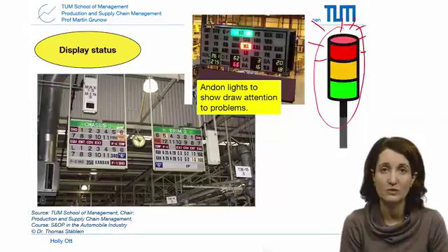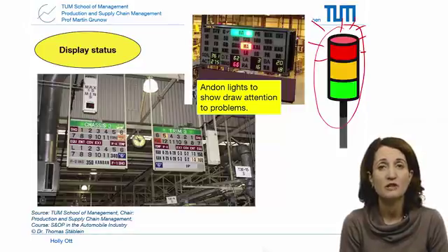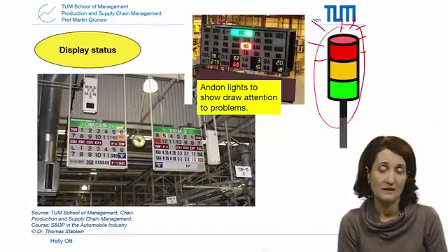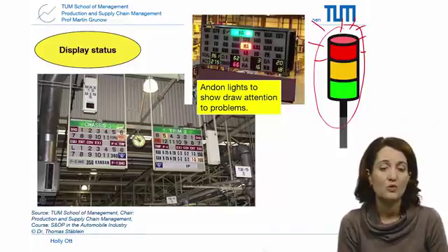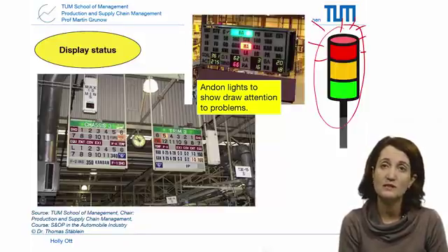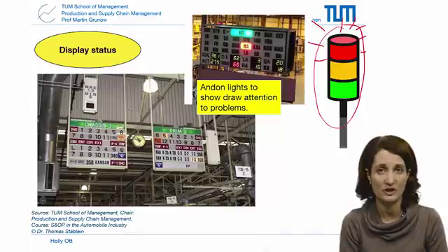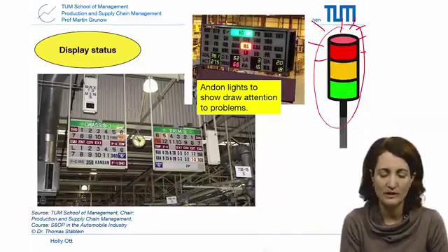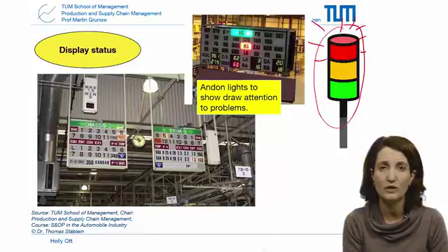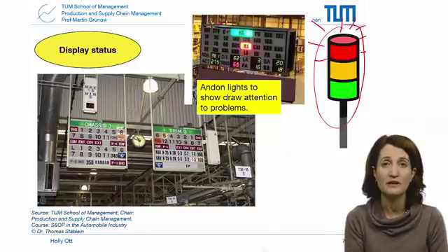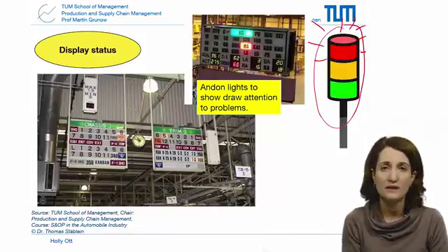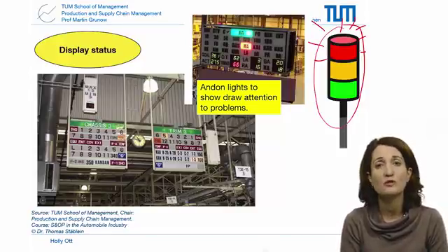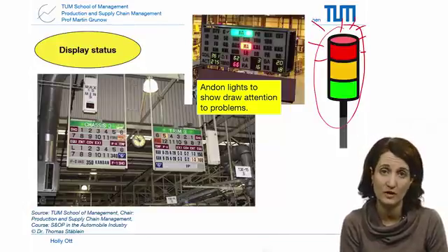What's very interesting here is the origins came from the original automated loom company. These looms from Toyota Sakichi would stop immediately if one of the threads broke. So the machine itself could distinguish between a normal situation and an abnormal situation. It's important because as soon as there was a defect, the operator would push the button or pull the cord and the line would stop. Of course, that means nothing can be produced at that time. But you're avoiding producing defective products, avoiding additional waste, and drawing attention to the problem so that hopefully the fix is quick and you can continue processing your good product.